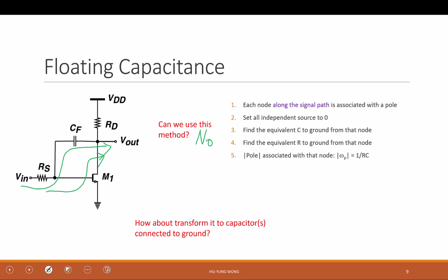And then of course the smart people, like someone called Miller, came up with something. Of course they have some very rigorous proof, but as an engineer, this is a good skill. You should ask yourself, the only thing stopping me is that this elevator only stops at the second floor. Can I model it as two elevators, or an equivalent circuit, that can bring me to the ground? The analogy is not too good now, but the question is: can I transform this circuit to something like this, where the rest is the same so that I still have the major function of this circuit?